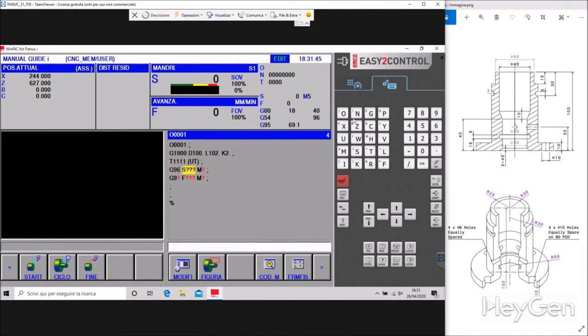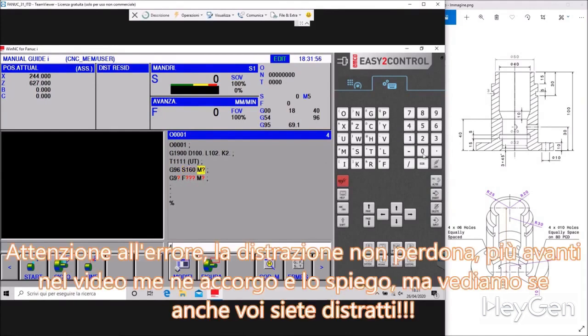I want to work at a constant cutting speed. Since we're doing a single piece with conservative parameters of 160 meters, and I want to rotate my spindle in M4. These don't concern us. As I said, I would customize it differently. Now let's talk about the first cycle.